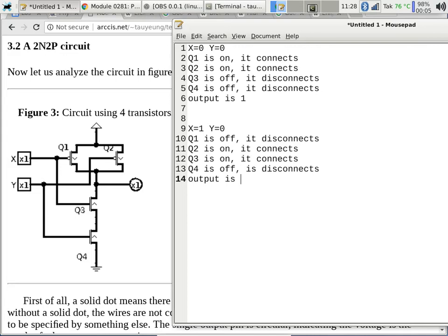Well, let's see if we can connect to the power, to the positive voltage source. Once again, we start with the output pin. We take a right turn this time. After we make a right turn, there are two paths to go. We'll explore the left path first. The left path goes to Q3. We look at this picture. Q3 is on. Good. Okay, I misspoke. It connects to Q1, but Q1 is off. It's disconnected. So the left path here is disconnected. Doesn't connect to anything. Cool.